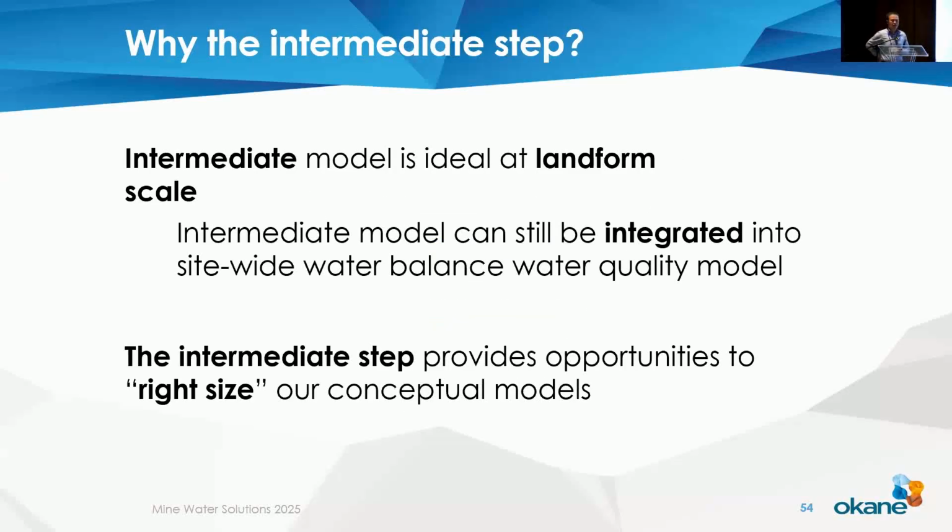So before I jump into the case studies, why do we want to do the intermediate model? It's really ideal for landform scale. So we're talking about a waste rock facility or a tailings storage facility at the facility level. And because those intermediate models have the right complexity, they can be integrated into your site-wide water balance, water quality model without significant effort.